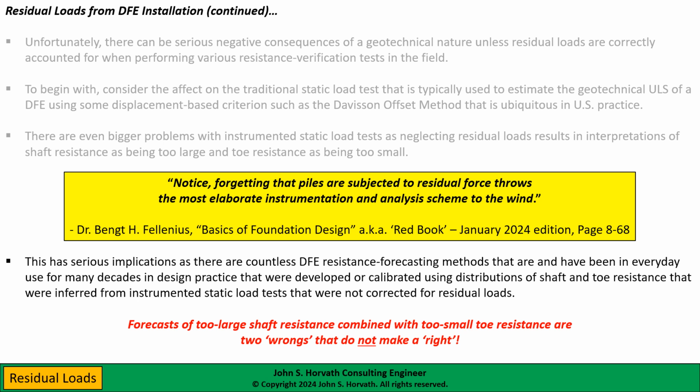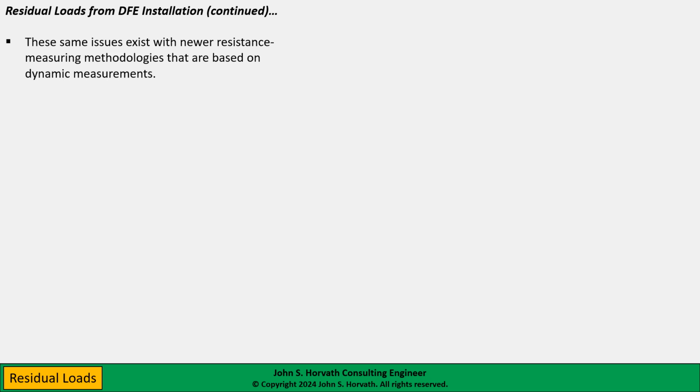Whether it's what we call an indirect method based on soil mechanics principles, or a direct method based on some correlation with, I don't know, SPT N values perhaps, like Nordlund did back in the 60s, or perhaps against cone penetrometer values, all of these correlations tend to be rather significantly incorrect.